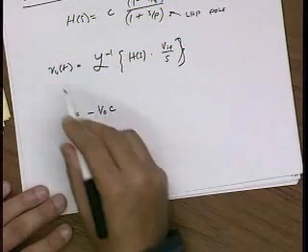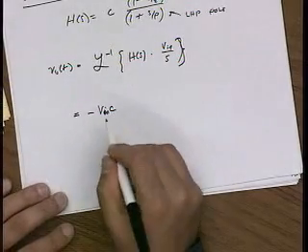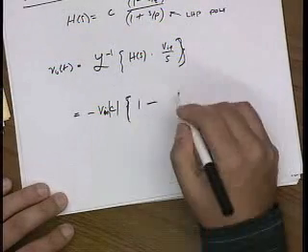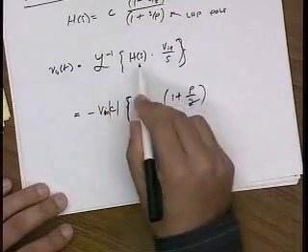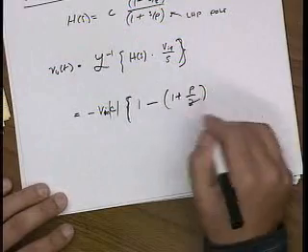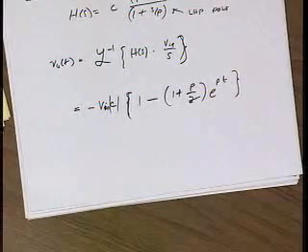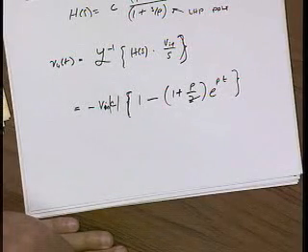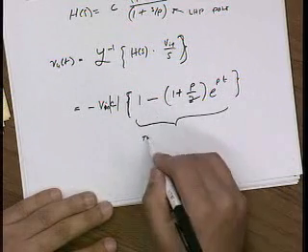The output in time is the input voltage times C, that's the gain. Say C here is negative, times the settling term. Basically, if you do a partial fraction expansion of this, you get 2 terms, and at the end of the day, this is the final answer that you get. All right, not too surprising. This is your error term, let's say. So this is our dynamic error term.